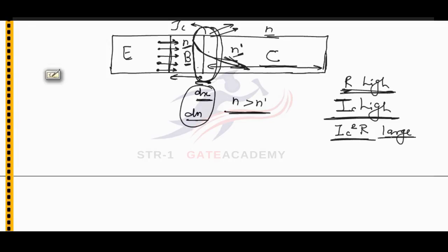and this much heat should be properly dissipated to the surrounding, otherwise the BJT will burn or will be destroyed. So this collector region is kept very large so that the large area of BJT should be in contact of surrounding. We cannot increase the area of a base, because if a base area is increased, then high concentration gradient will not be created.